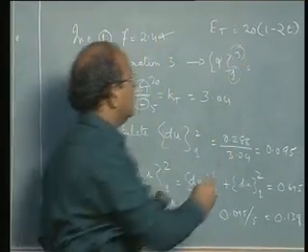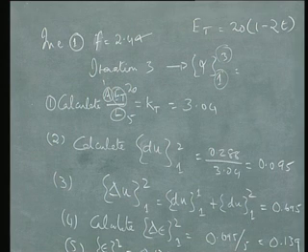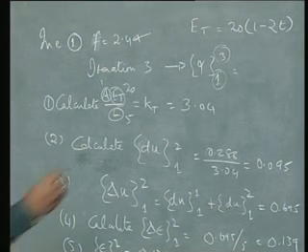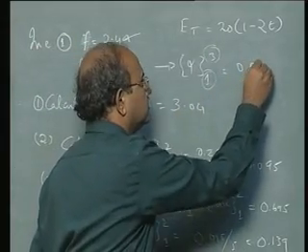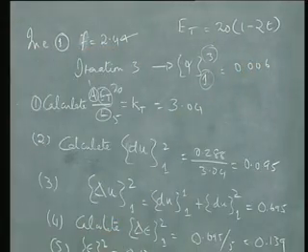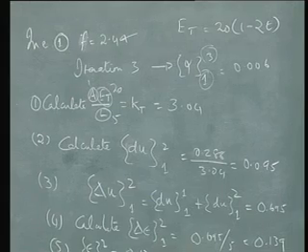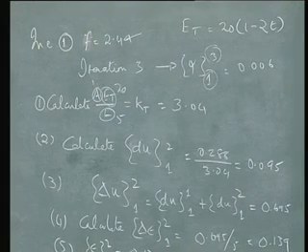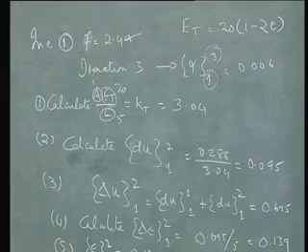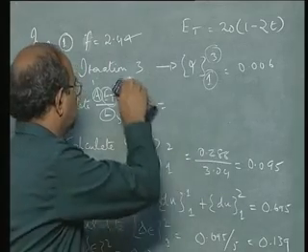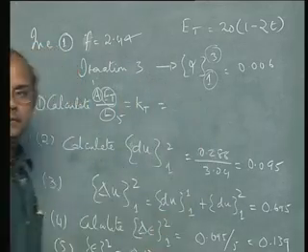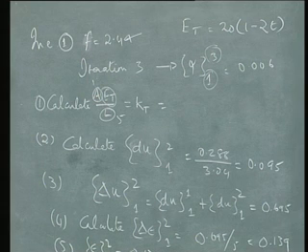What is the error which we calculated? That is 0.006. So that becomes 0.006. I hope the procedure is clear. Okay. Any questions? Okay. Now calculate ET and calculate KT. The new KT we have to update. We are doing full Newton-Raphson procedure, and hence calculate KT and tell me.